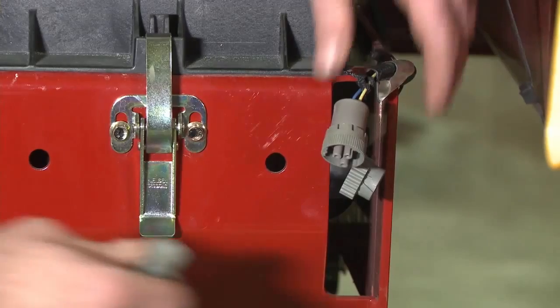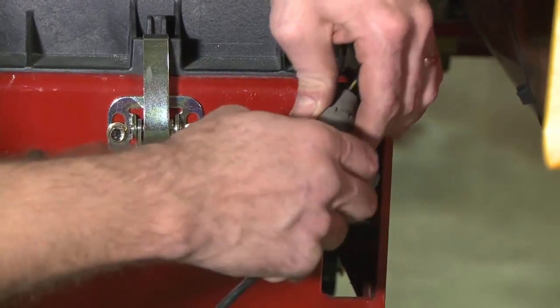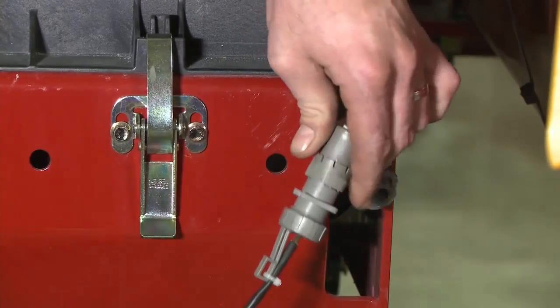Industrial technical training. Today we're going to be talking about the calibration for the early riser planter liquid fertilizer system. In preparation for the calibration, make sure the calibration switch has been plugged into the planter electronics. Also, it's important to make sure orifices have been selected for the liquid fertilizer nozzles and have been installed before the calibration process is completed.